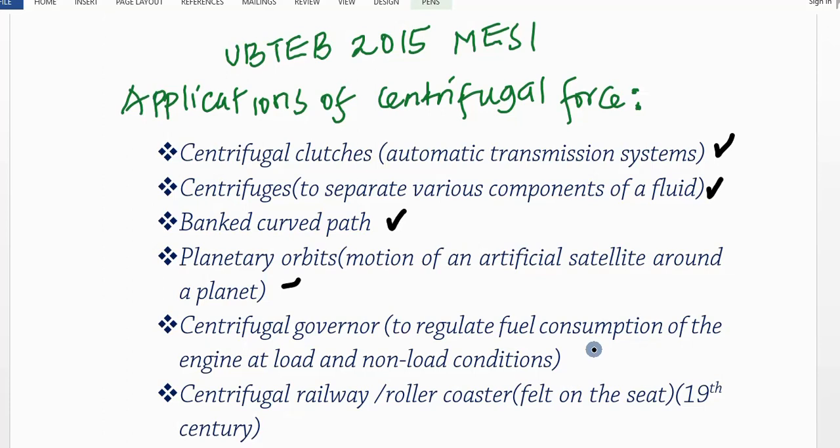So when they rise up, through the mechanism through which it has been designed, for example the spindle moves up, through the links connected via the crank to the throttle valve, it pulls down the throttle valve, thereby reducing the amount of fuel going to the engine, and this reduces the speed of the engine.